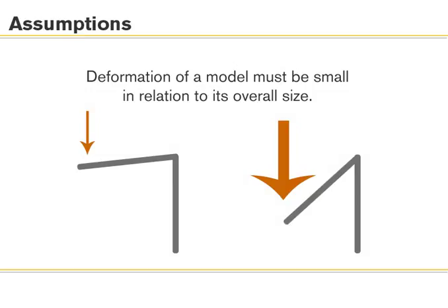A symptom of this is unexpected stiffening of the part due to deformation, much as a guitar string gets stiffer as it's stretched. If you're concerned that large deformations might be impacting your results, you may need to explore the response using full SOLIDWORKS Simulation.